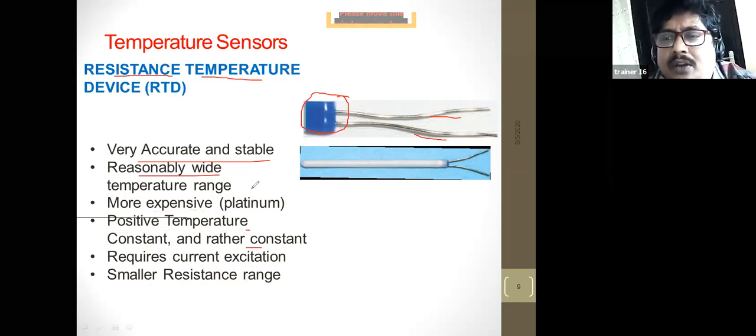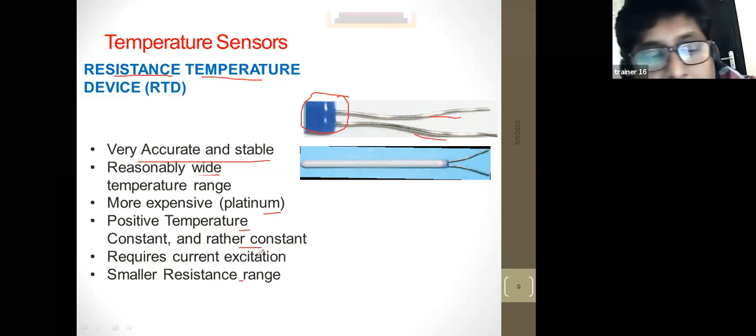This is also a similar resistance temperature detector. Here there will be a change. It is also made up of platinum. It is exposed where the temperature of a liquid or a gas has to be measured. Then automatically there will be a change in the resistance of this element, which is connected as one of the resistors of the Wheatstone bridge. Then you can get the voltage, which in turn leads to the temperature parameter.